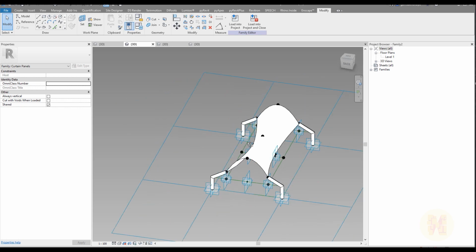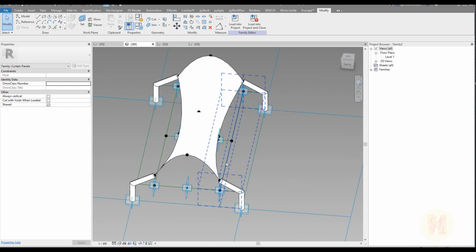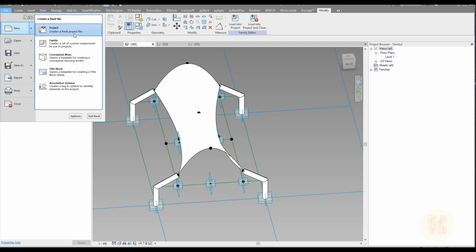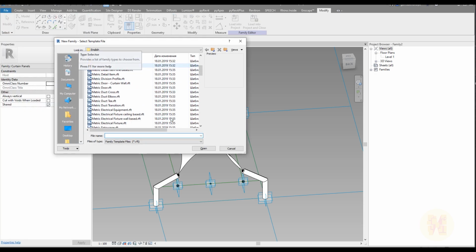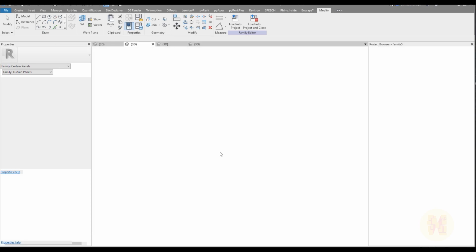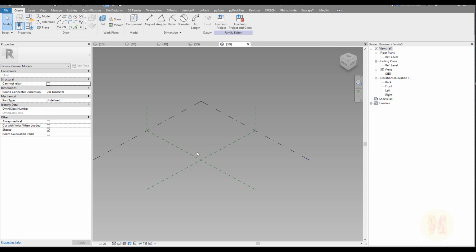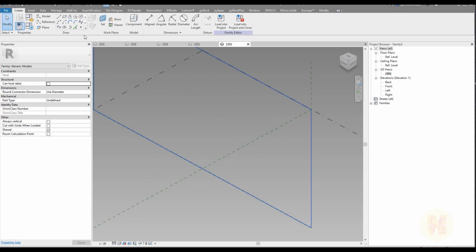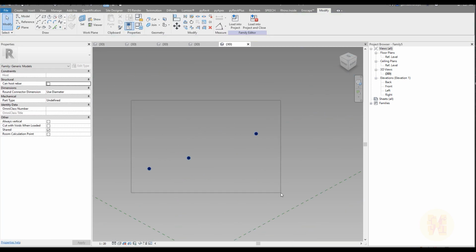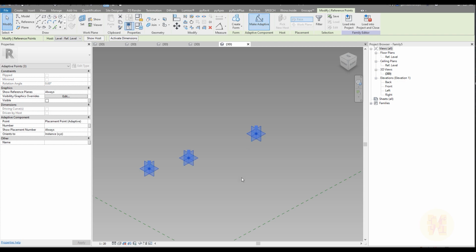But it's not finished. We should create one more thing. Let me create one more adaptive family. As I said, today will be a lot of adaptive families. But don't try to create an adaptive family inside an adaptive family inside an adaptive family. This will be worse. Try to create only one level, so in one adaptive family, only one adaptive family, not more.